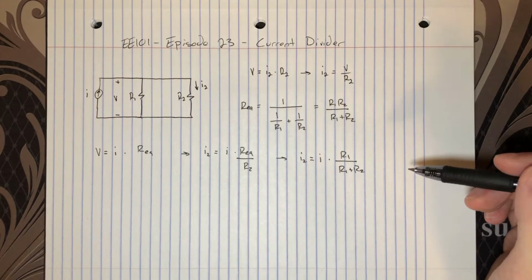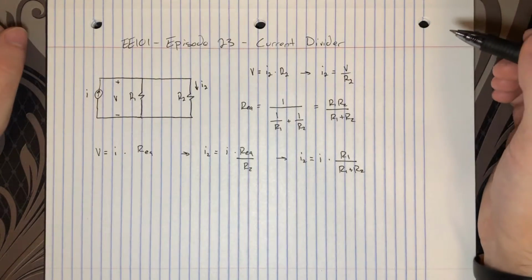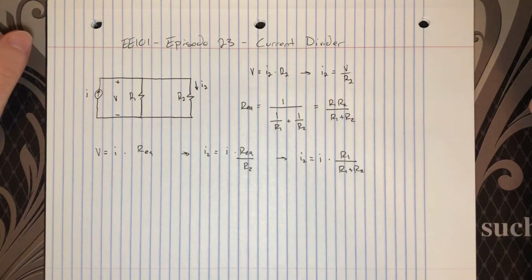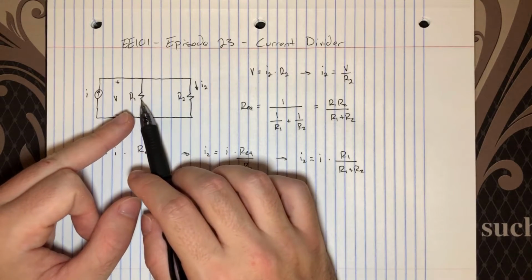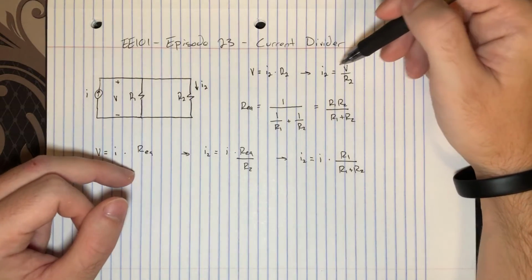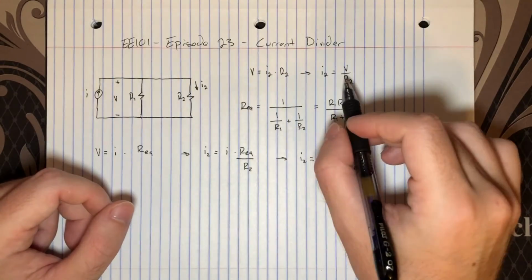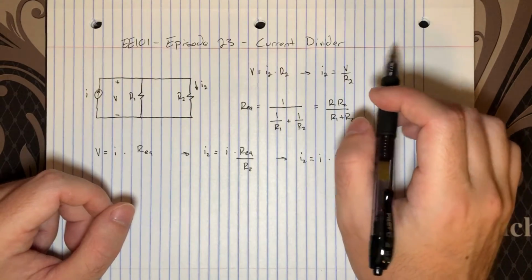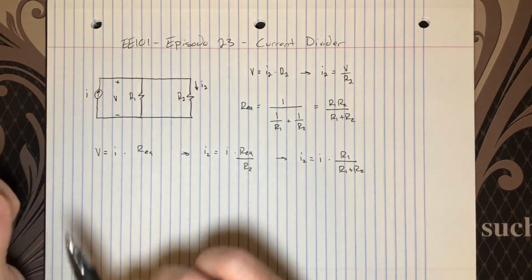And that seems kind of weird, but if you just think about how current flows and the physics behind Ohm's law, it makes a lot of sense. So it becomes clear when you start thinking about the limits of these resistances. So if you have some resistance R2 and then let R1 get infinitely large, well, you know from Ohm's law that I2 is the ratio of the voltage and the resistance here. So if you just look at Ohm's law here, as R goes to infinity, this expression goes to 0. So yeah, if you have an infinite resistance, no current can flow through it.